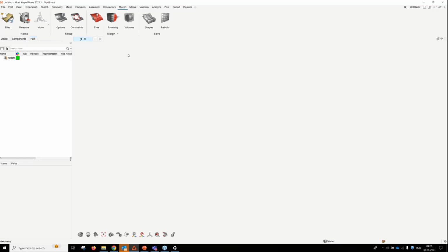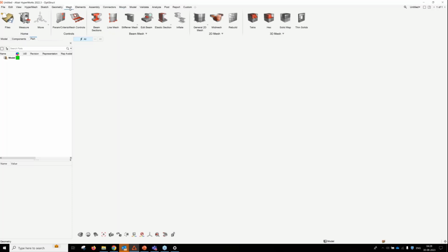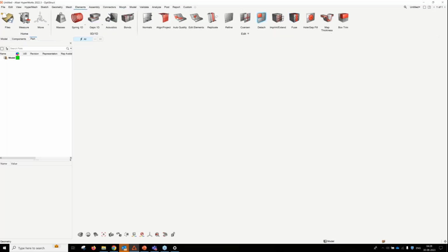Apart from morphing, we also have the majority of the tools in the geometry and edit element. We have a lot of functionality to edit elements. It's all just dragging or double clicking. If you want to edit anything on an already created element, if you want to drag it, it is on the go. If you want to change certain densities on the nodes, just click the edge, copy the same density values, and paste them onto a different edge. There are a lot of things we support as of today.